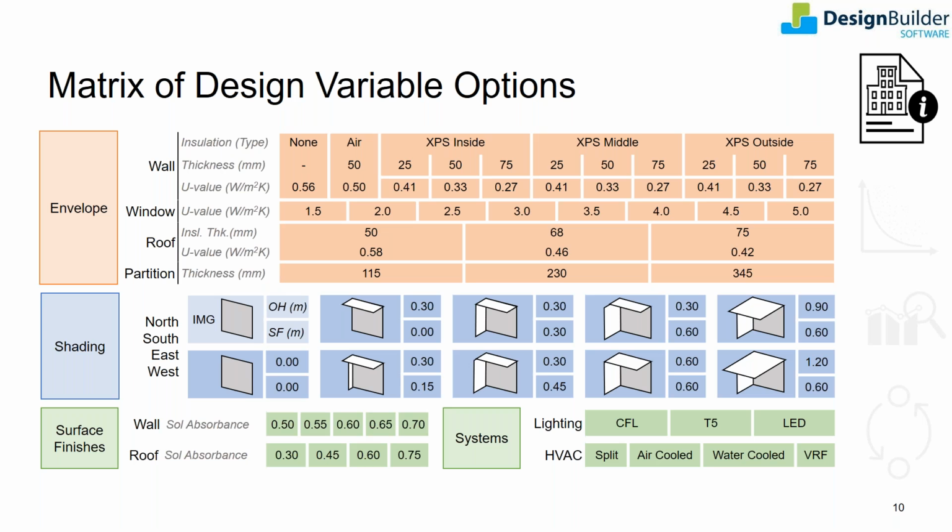Besides U value, another option related to the wall is regarding the external surface finish. Solar absorbance of the outermost material was taken as the variable. Reflective surfaces reduce the cooling energy use significantly and can be achieved at almost no cost implication. However, they are more difficult to maintain and might not be aesthetically desirable.